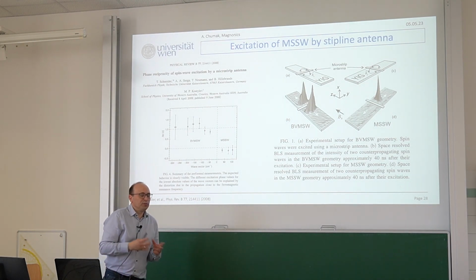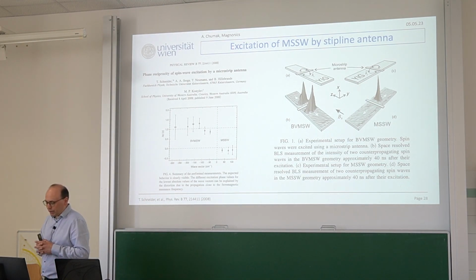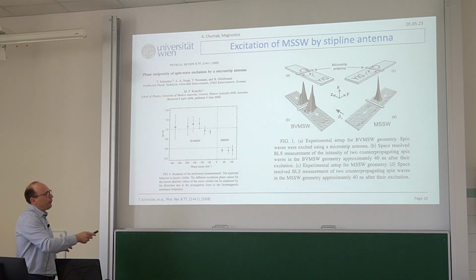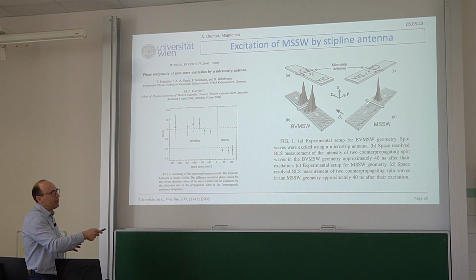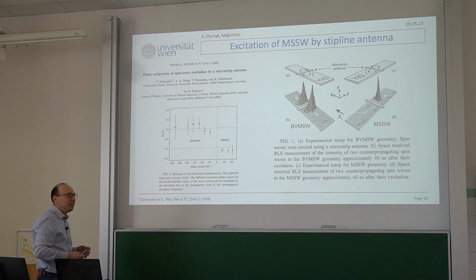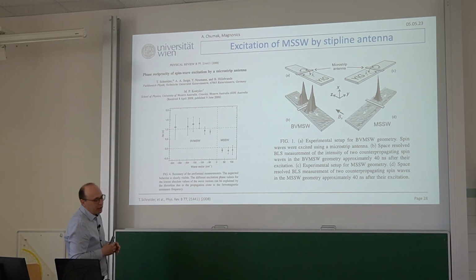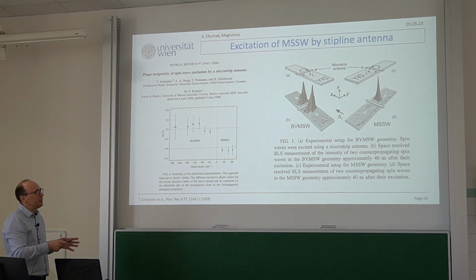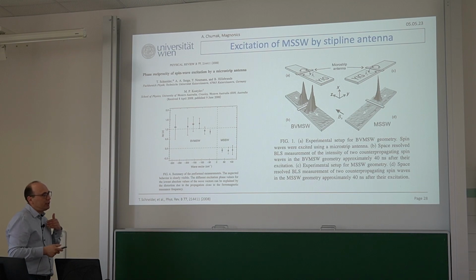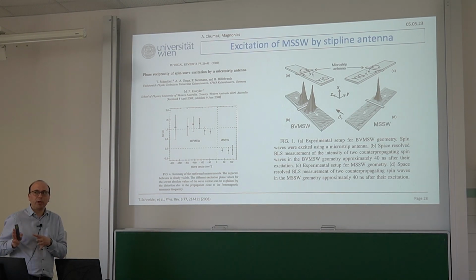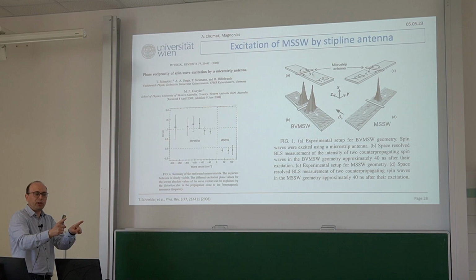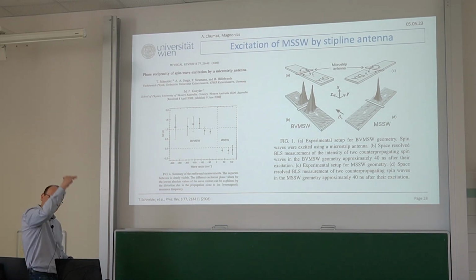So principally, to give you the finger kind of explanation, it means that all this complicated excitation mechanism here will be in phase for a wave propagating in one direction, and it will be in antiphase for a wave propagating in the opposite direction. Therefore, we have such situations that Damon-Eshbach is, in such simplest case, excited preferably in one direction. So in your experiment, always check when you measure the S21 parameter, check also S12 because it might be much larger.